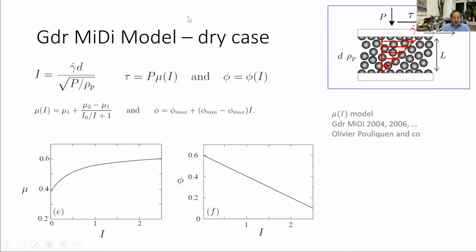So what is this model about? I just put it here in a very, very short form. They consider tau as the shear stress, a function of the normal pressure, right? And then the shear stress and the normal stress are proportional. And you would say, fantastic, this is not really new. Mohr-Coulomb is just like this. Wait a moment, there is something new, right? This proportional factor, in our case, would be the friction angle, tangent phi. But here it's different, and they call it mu I. That's why sometimes this model is called the mu I model, right?